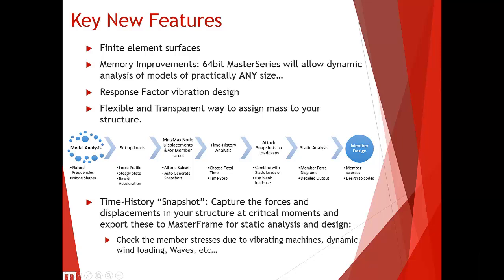And we've also improved one of the time history analysis features, which is called our snapshot. And this allows users to capture the forces and displacements in their structure at critical moments and export these to MasterFrame for static analysis and design. And we've added features that make it much easier to generate these snapshots at the critical times. And I'm going to go through an example of this shortly as well.